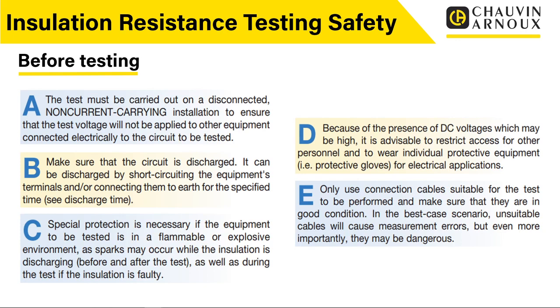Always with your test equipment, again, make sure it's in good condition, make sure there's no signs of damage, make sure it's all clean and dry, particularly if you are carrying out these tests outside, and it might be wet and things like that. You've got to be very careful to make sure that you're not in that environment when it's going to become dangerous. So always ensure that you have looked at your environment, you have looked at test equipment and made sure that it's safe to proceed. So there are a lot more precautions we could have talked about before testing, but that's really a good overview of the things that you need to think about.